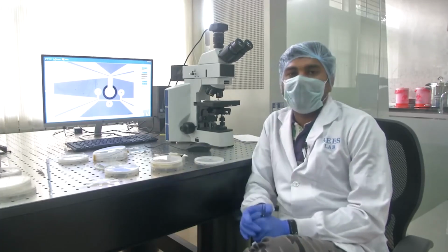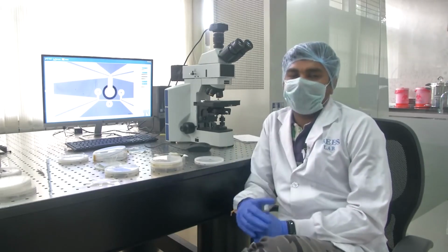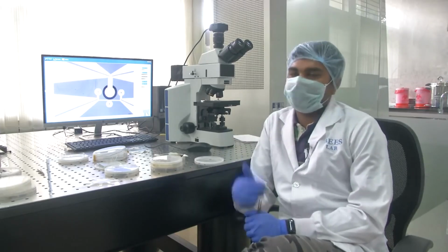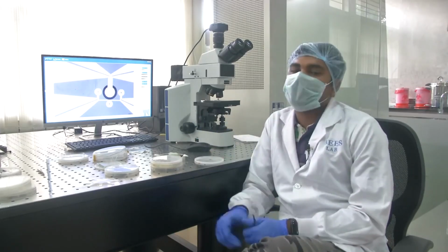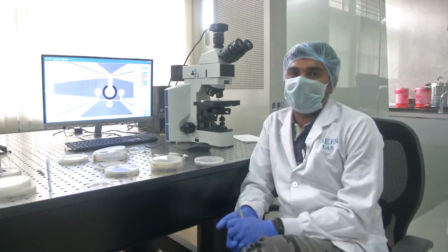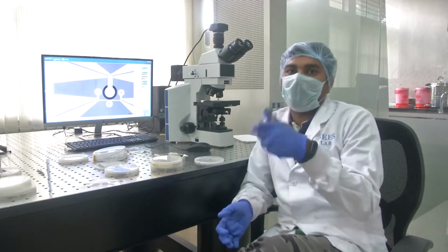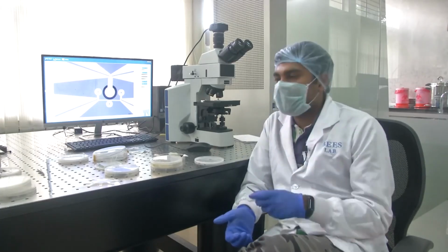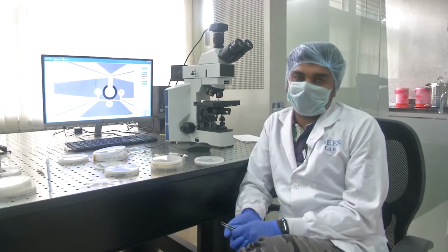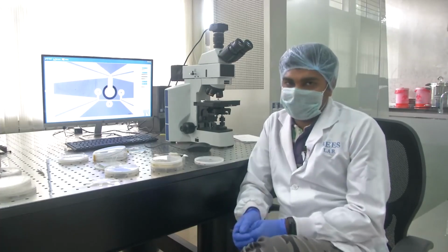We have shown you how we have made a sensor with platinum using the lift off technique, how the process was done, how that wafer was diced using an automatic dicing machine. We don't have that machine in our premises, so we just spoke to you about that. Then how it will be stuck onto a sticky material, and then you saw the dicing lines on the substrate. Then I took out one such sensor. I showed you that sensor in my tweezer, and we looked at it under the microscope also and saw how functionally it might be useful for any sensing applications.